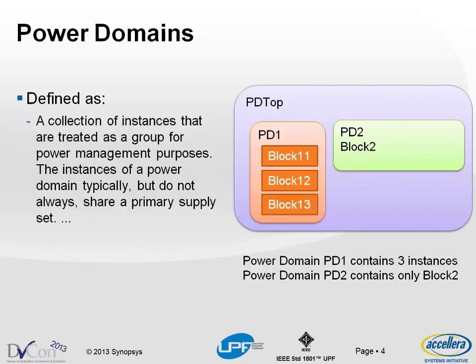Now, you'll notice here I've got a power domain for the top, a power domain for this block, and a power domain for this group of blocks. What this is telling you is that you don't really have to keep a strict one-to-one correspondence between a logical hierarchy and a power domain. You can have multiple logical hierarchies belong to the same power domain. But the key is, a power domain is a grouping of logical hierarchies.